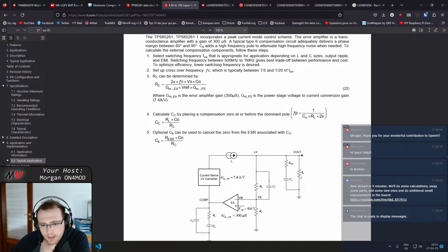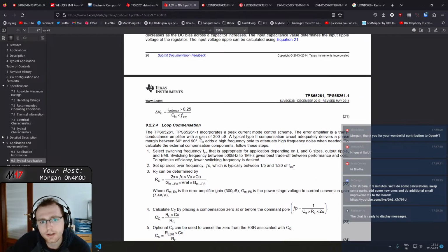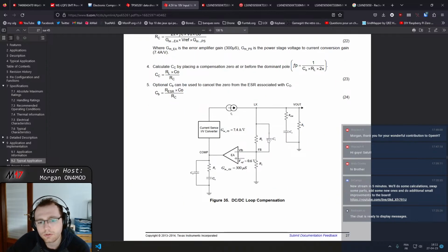So first, they give the load resistance, so as if the load was a simple resistance, which in this case is not that much of a problem, because we consider a kind of small signal circuit, which means that we consider small changes around the fixed value. So we can consider that the load can be approximated as a resistance, which will change, by the way. However, you see that there is the C1 right here, and nowhere do they give a value or an equation to compute this value.